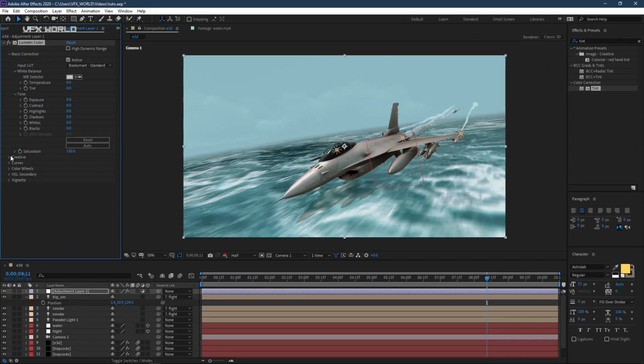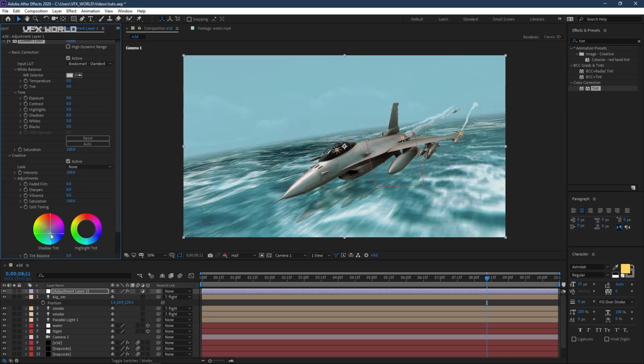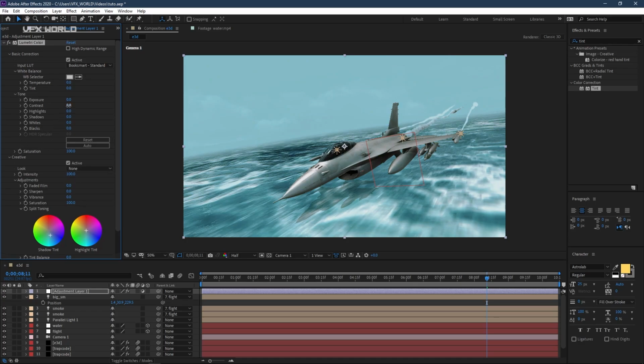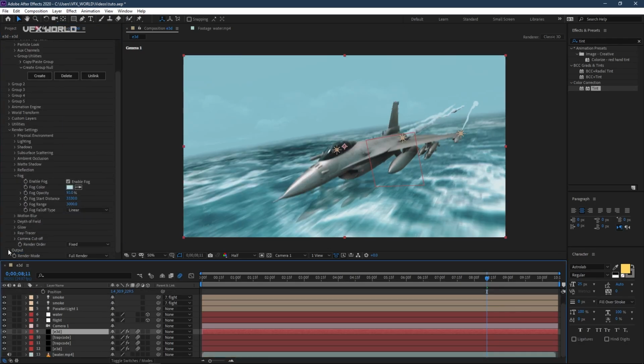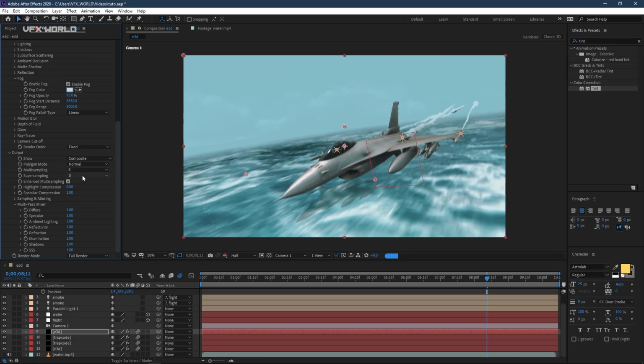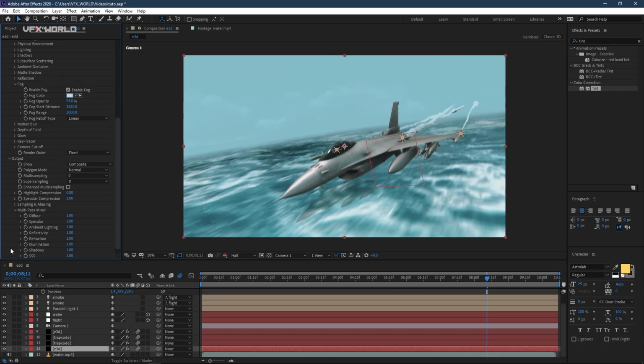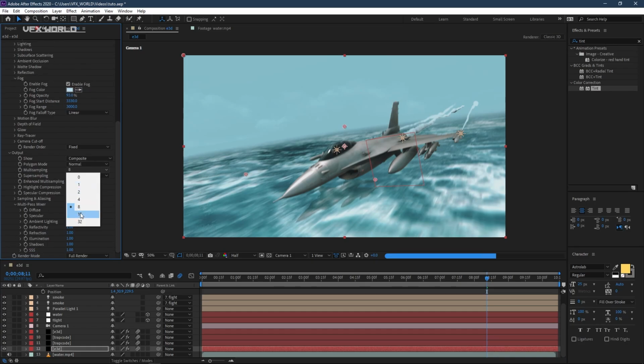And after importing that, we have to change some settings a bit, like make it a bit blue, something around this kind of color correction, increasing the contrast a bit high and making some faded kind of effects, and turn on the motion blur, and that's it. And now select Element 3D for the top one, go to outputs and just increase the multisampling. Same thing for the background layer as well, go to output and turn this on and make it 16 and 100% and all.